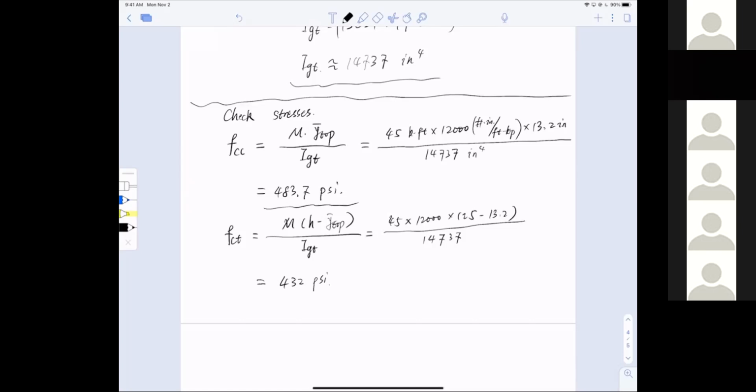Now, moment of truth. I find this number to be smaller than the modulus of rupture I previously calculated, which is 475 psi. So the uncracked assumption is proved. Hooray, we're good.